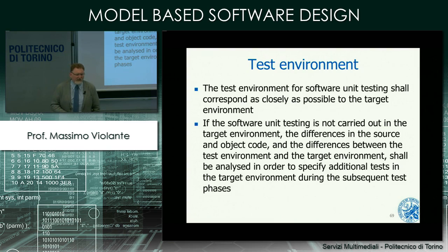You are writing a function in a complex algorithm that is going to be deployed in an electronic control unit that is going to be inserted in an engine. And you have a team of 50 developers. You cannot imagine that each developer has its own engine to do the test, too expensive. And you cannot imagine that each developer has to queue for accessing the single engine that is available in the factory. It will take too much time. So you need to find a way for providing the software developer with a working environment that resembles the actual environment. For this, we will do hardware in the loop testing.